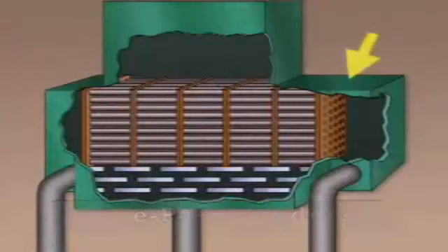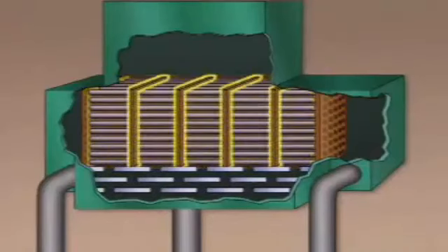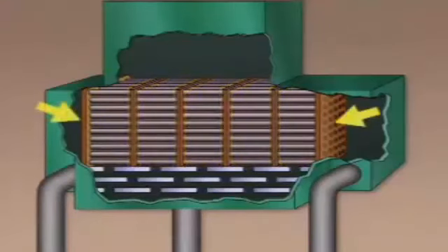The condenser shell forms an airtight casing around the entire condensing region. Inside the shell is a tube section, which consists of hundreds of circulating water tubes. Plates called tube supports help align and support the circulating water tubes. Components called tube sheets support the tubes at their ends and separate the steam in the shell from the circulating water in the water boxes on each end of the tubes.